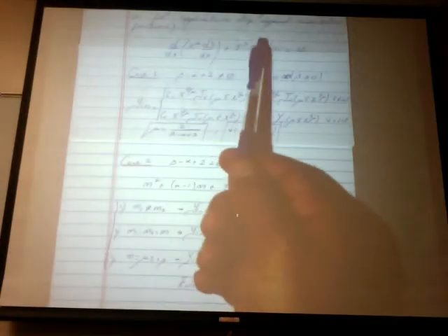And the problem engineers work on is the optimization of the solution, the optimization of the amount of heat transfer that you can remove from a section. Optimizing the heat transfer will be, well, kind of inversely solving this equation by maximizing the amount of heat that you want to achieve. That would lead to the optimal coefficients alpha and beta that you would need on this equation so that the heat is maximized.